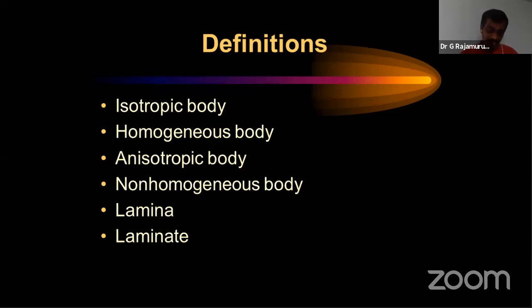Again, in reverse, if the end user is asking you to fabricate a composite for a high temperature application, then your composite should have excellent thermal resistance at higher temperature. You should keep that property in mind, and select the appropriate matrix, the appropriate reinforcement, and the way of fabricating this composite, whether you go for a strip casting method or a vacuum compression method.